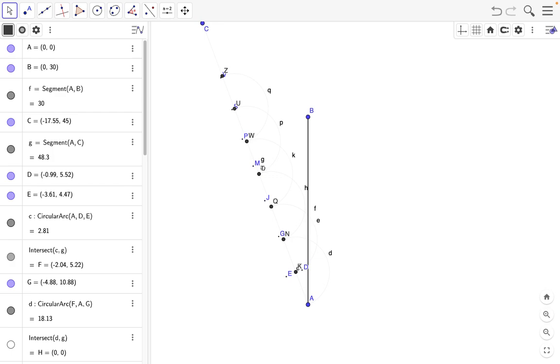Now I had taken AC as an arbitrary line. So I had divided AC into an equal number of divisions, not up to AC, part of that AC. So from this point, then this, so equal number of divisions I have got up to Z. Now I will project or map Z on B. So we will map Z on B. If this end and this end of the arbitrary line map, they are already mapped. So the points in between will map if we draw parallel lines, that is the concept.